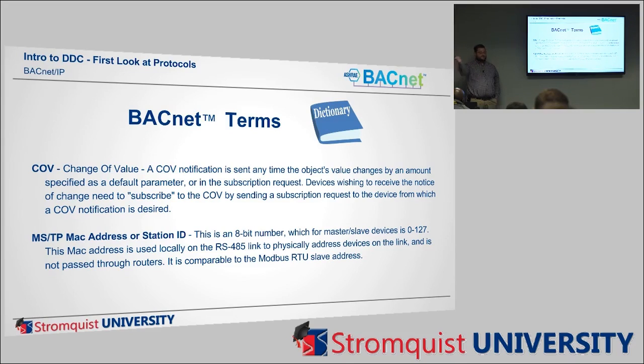So I don't need to put traffic along my bus polling this piece of equipment or this sensor every second to get an update when it only changes at 1/10 of a degree. So you use COV and you say if this value changes more than whatever you set it at, I go tell the controller you need to come get my new value.